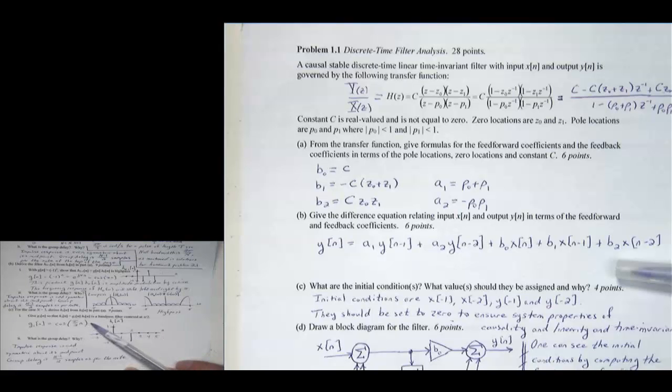Because what is this? This is really an LTI system with a pole on the unit circle. Two poles, one at pi over 2 and one at minus pi over 2. And it's a two-sided impulse response. BIBO unstable.